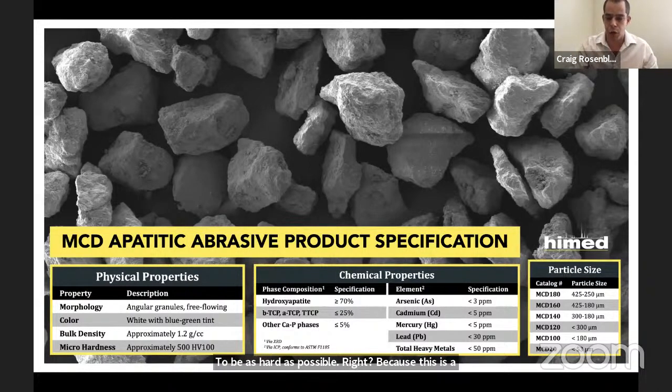Contrary to other materials like aluminum oxide, silicon carbide, and other ceramics that are not compatible, these materials cannot dissolve away from the surface, and blasting with them will result in embedded foreign materials.